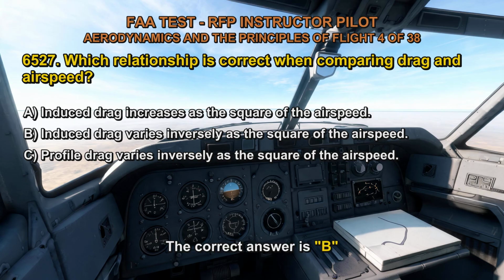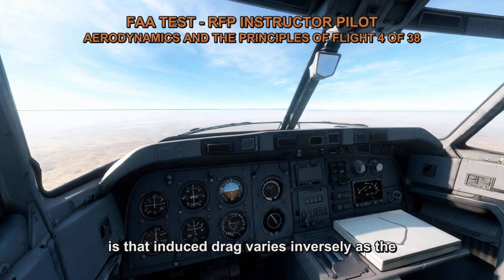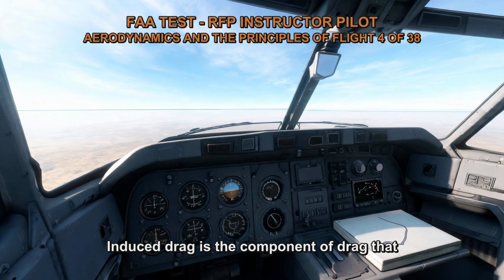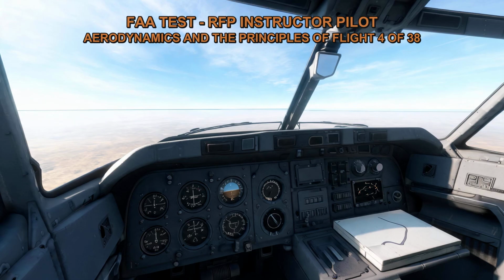The correct answer is B. The correct relationship when comparing drag and airspeed is that induced drag varies inversely as the square of the airspeed. Induced drag is the component of drag that is generated as a result of the production of lift. It is caused by the creation of wingtip vortices and the associated downwash.